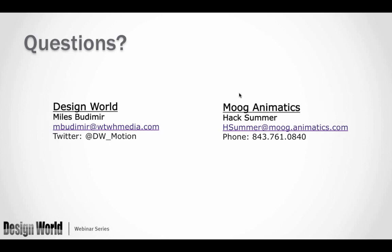That's a further limited spec below the OSHA shock level that says a person may come in contact with this product in the water. Maybe it's something that moves in a swimming pool, a nozzle that pushes water around or sprays around, whatever. In that case, we actually meet that specification as well. Not many people have those applications, but if you're at a theme park or some display in front of a hotel, as I used earlier, definitely you need to meet that below 30 volt spec, and we do in fact meet that specification.